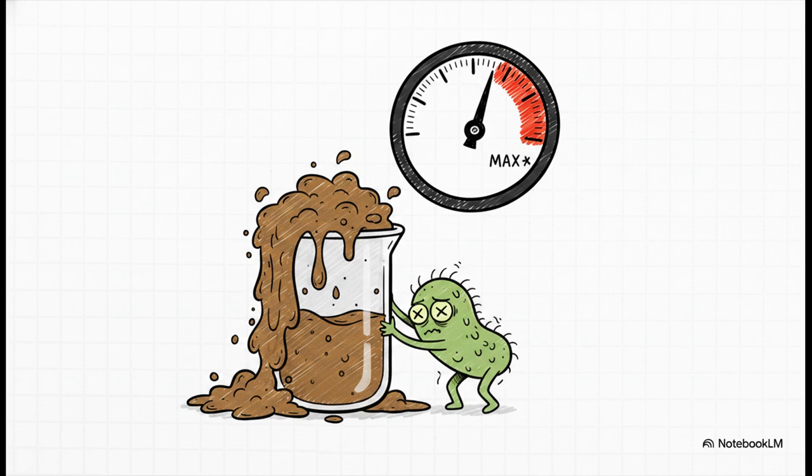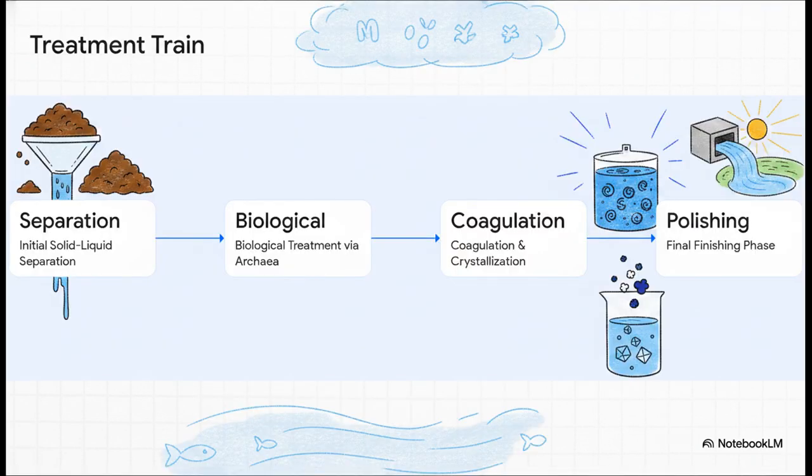Relying on just one single microbial additive to close that massive mathematical gap, it's technically impossible and frankly mathematically unsound. You absolutely have to design a complete, integrated system. Therefore, you've got to treat Archaea water as just one highly efficient element within a mandatory multi-step treatment train to guarantee safe discharge. There are no shortcuts here.